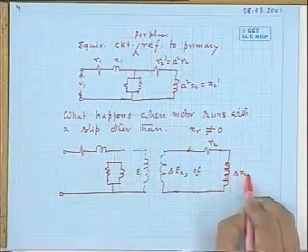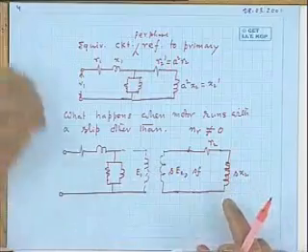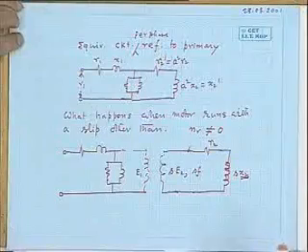What should I write here? S into X2, because this also will reduce by the same factor, because 2 pi FL, whatever is the leakage inductance, that is X2. So another S comes. Where X2, remember, is the standstill reactance, and S is the slip at which the machine is operating.